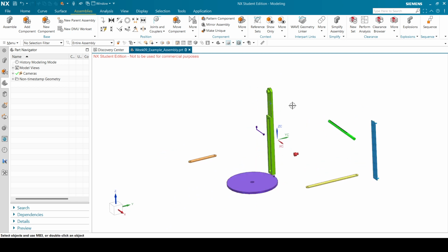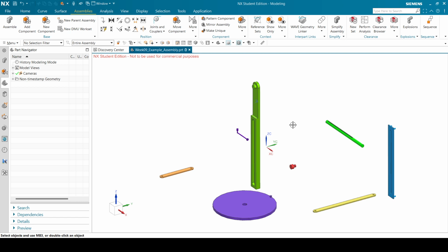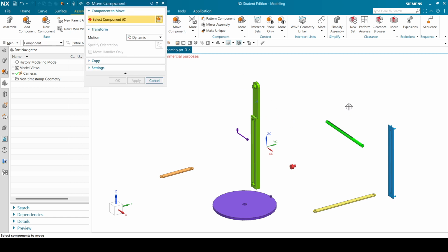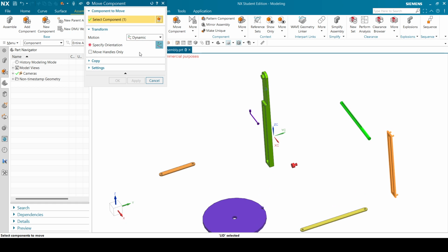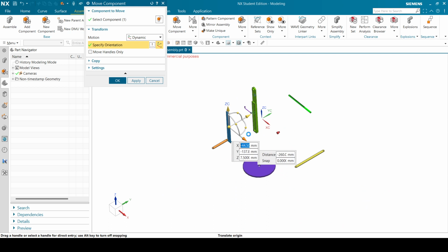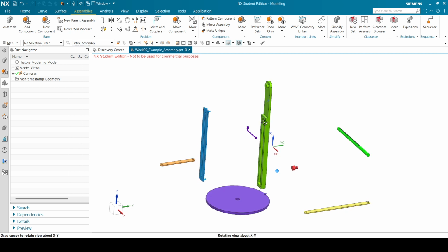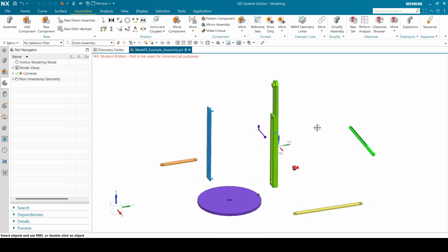Okay, so part of creating assemblies in NX, especially when it's an assembly that someone else created or parts someone else created and you have to assemble, is to just apply common sense. I'm first going to move this component close-ish to where I want it. So this, at least on the right side of the green part, or the base part. I'll just move it over here, and it's close enough. Also, something that changed since the previous version of NX I did assemblies in is that now they don't just snap parts to where you constrain them to.